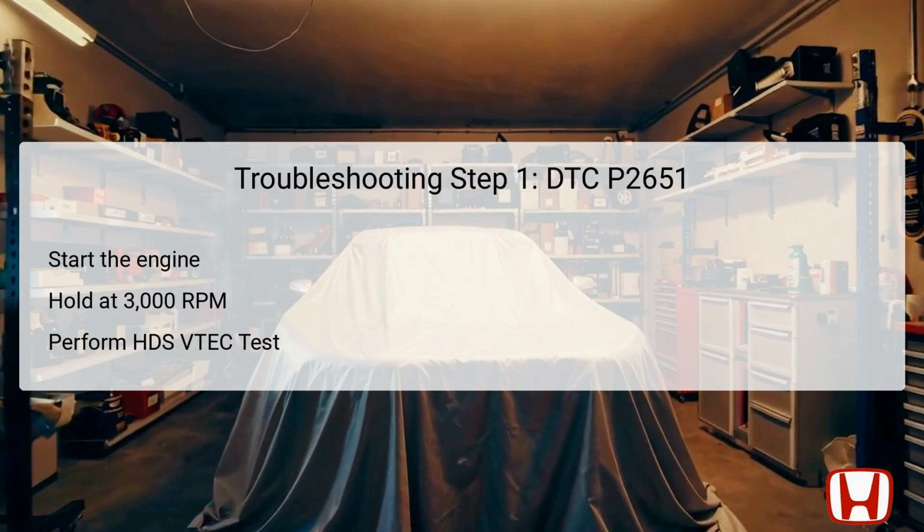The first step in troubleshooting DTC P2651 involves starting the engine and holding the engine speed at 3,000 revolutions per minute, RPM, without any load, which means the vehicle should be in park, P, or neutral, N. This elevated RPM is maintained until the radiator fan activates, indicating that the engine is reaching operating temperature and that sufficient oil pressure is building in the system. The next action is to let the engine idle to observe any changes in the pressure readings.